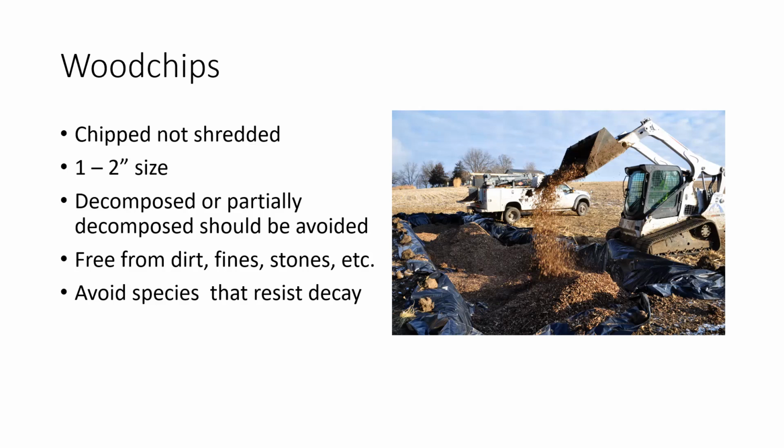It can get pretty costly pretty quick when that happens. So we look for a chipped material, not shredded. They are starting to look at shredded options, but that's really not into the standard as of yet. You can probably do it if you tweak your design, but more often than not, chipped is safer right now. It'd be nice in the future if we could start moving towards a shredded material, just because that's more readily available, especially with municipal piles being out there. And generally, they're a little bit less expensive than the chipped material. But for now, the safest bet is to use a chipped material.